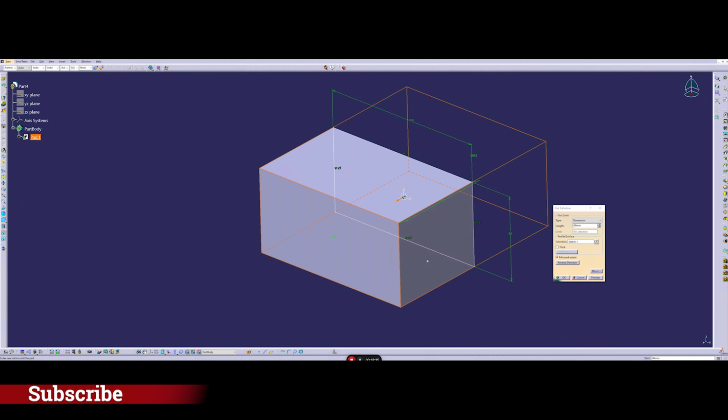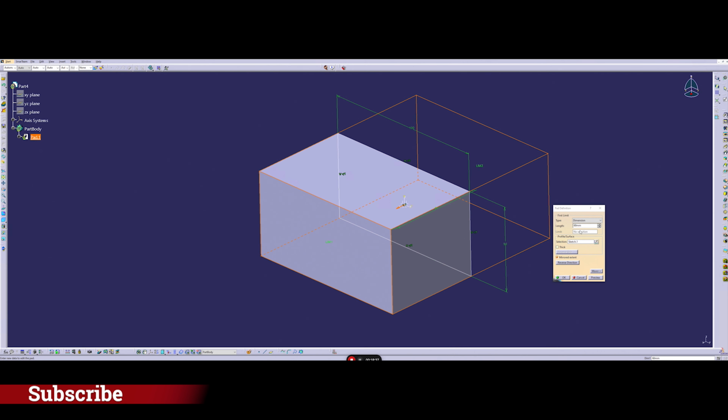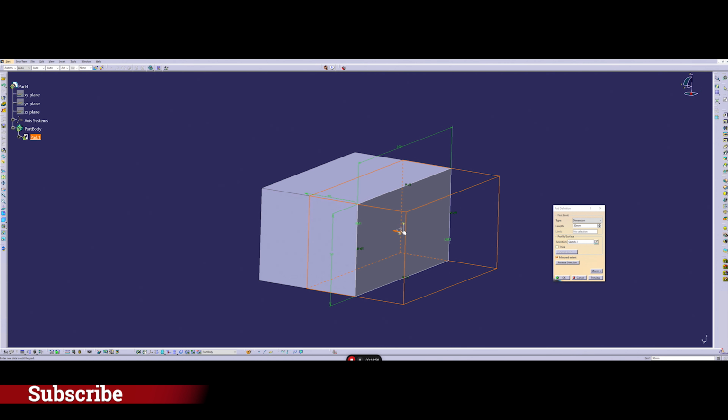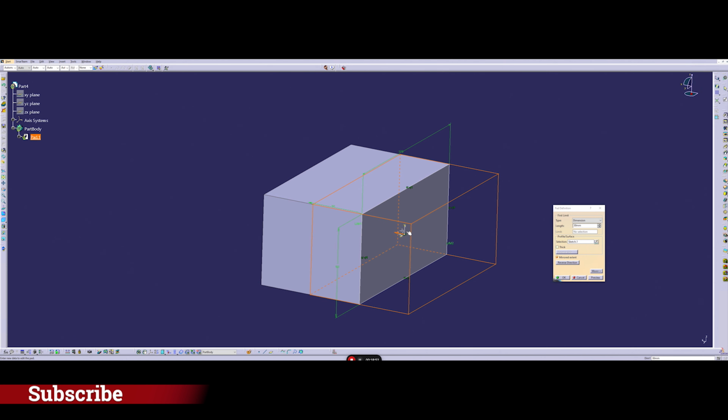So with mirror extend, if you want to have a piece of 60 millimeters, you have to be sure that this will be 30, because don't forget you have a mirror extension, defining the center of the extension as the origin here.